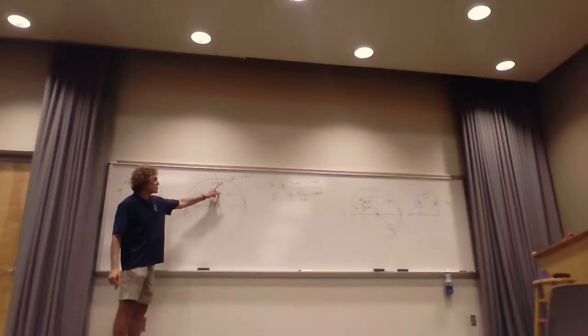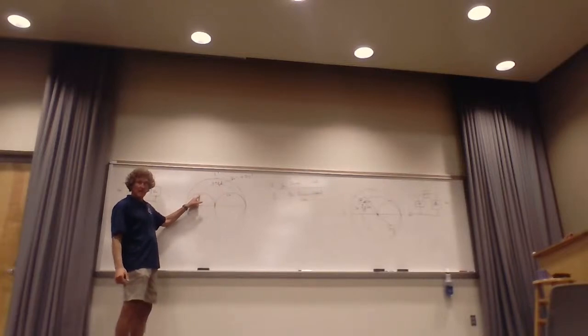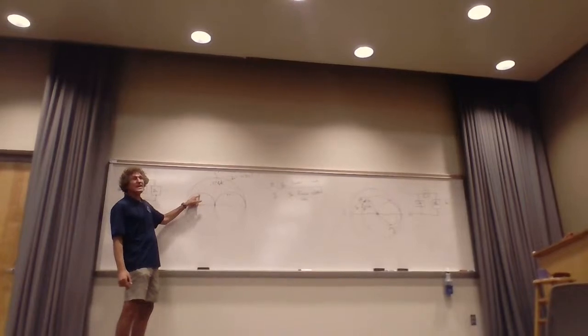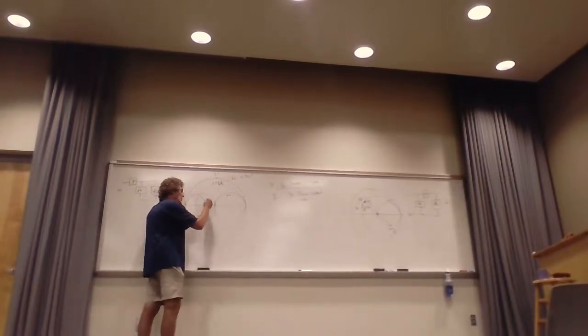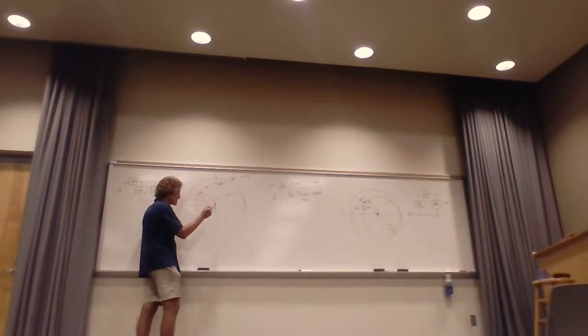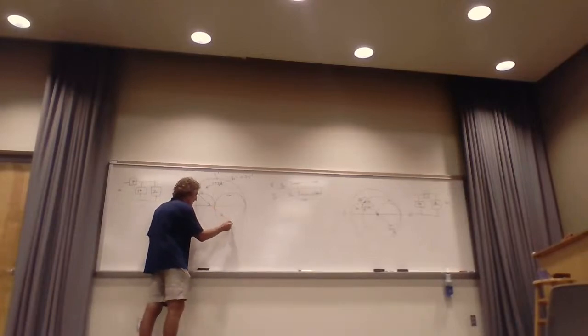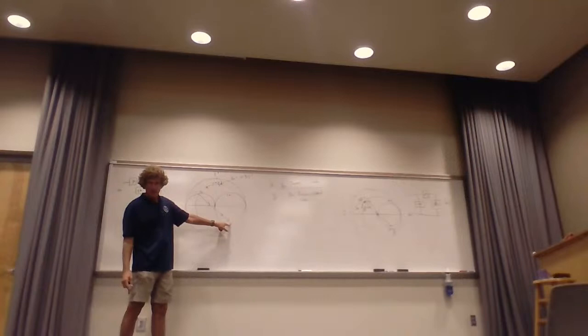Remember, by adding j, I can move until I hit here, right? Y'all agree with that? That would be an impedance, correct? That would be a series impedance. I can hit this point, and then I can go from this point to the admittance domain. By adding impedance here, in series, then taking 1 over that, now I'm on the rim, that's admittance. And then I add a plus j admittance to get to here. Y'all follow me?